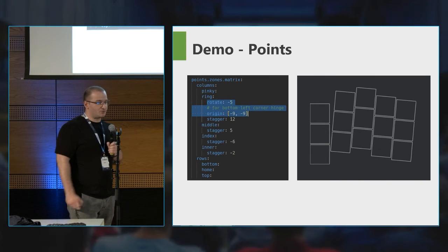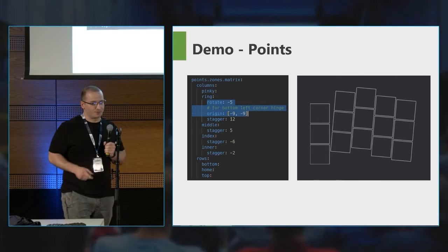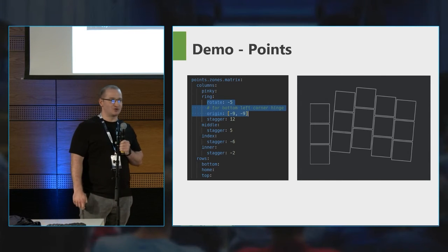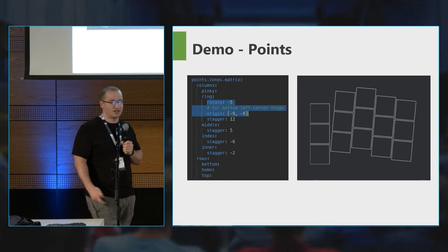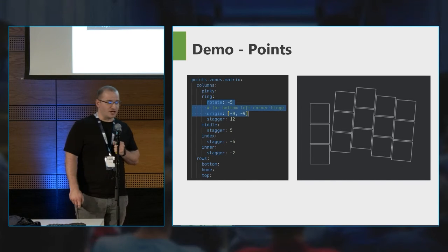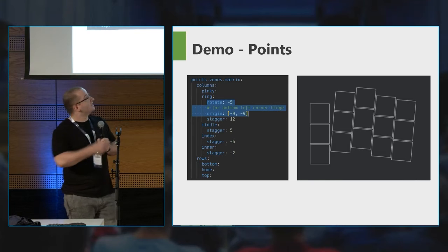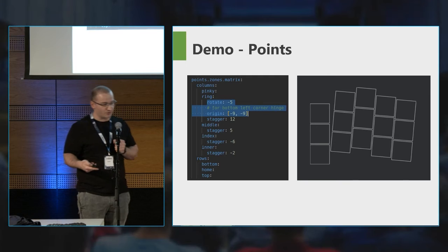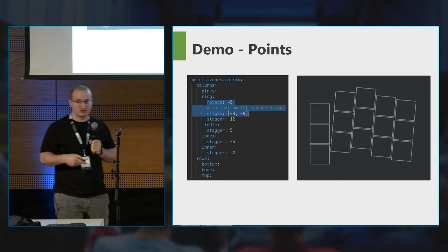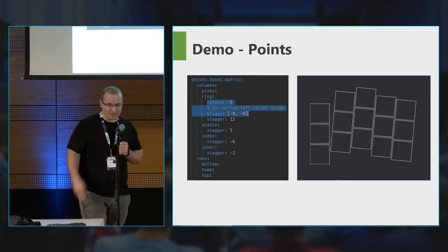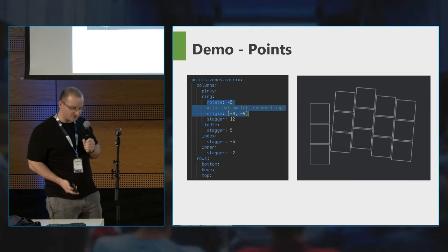And if we also want to add the signature pinky rotation of the Absolem, we can do so by introducing rotation and origin, which are also key-level attributes like the stagger that we used previously. So with it, the pinky is just the plain pinky column, but at the ring, we add an extra 5 degrees of rotation with the bottom left hinge, so it changes everything else that comes after that. And this is how the pinky is separate from the others.